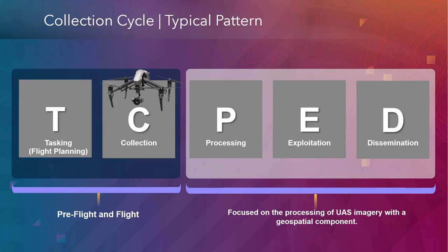We take the individual images and we process them into GIS-ready products. So those orthomosaics, those elevation models, those terrain models, they all come together in one system. Once we've got that, then we start to understand how that imaging is affecting our site. So things like being able to do volumetric analysis, profile analysis, do time enabling across a period of time, multiple flights, those sorts of things.